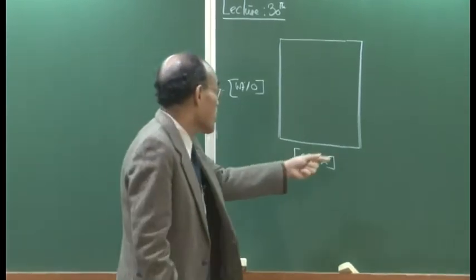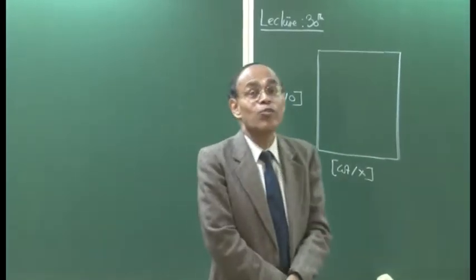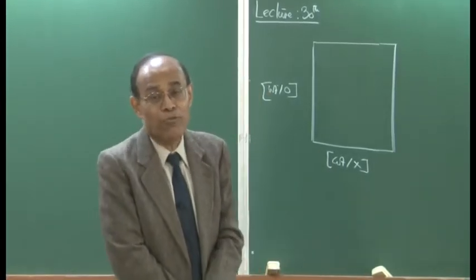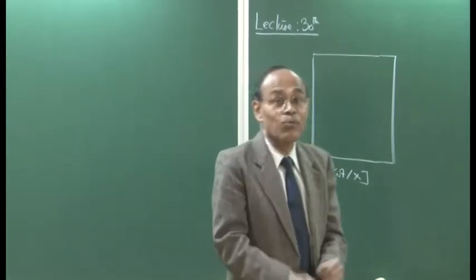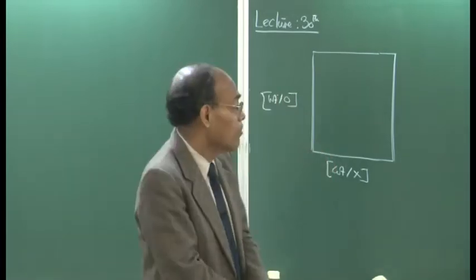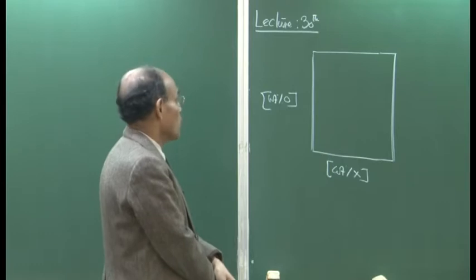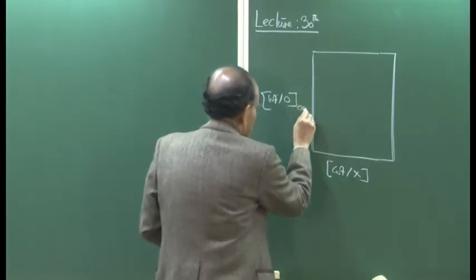This axis is logarithmic and this is logarithmic scale, and then you can imagine that you will always get a straight line, because for example, if you write the aluminum deoxidation reaction, then aluminum raised to the power 2 will become 2 log aluminum, and similarly oxygen raised to the power 3 will become 3 log oxygen. So, you will get a straight line, and these are all equilibrium values.